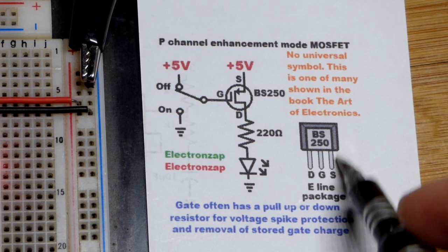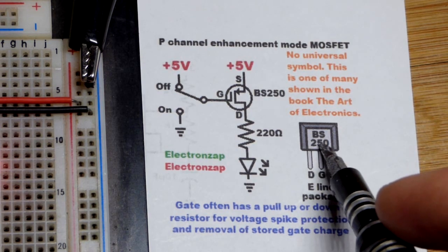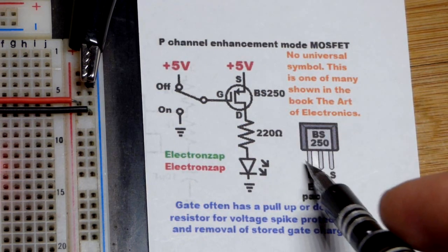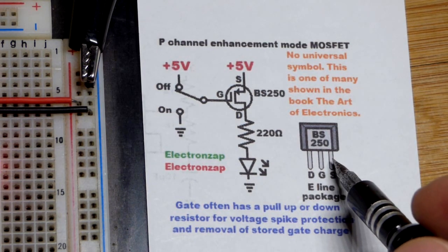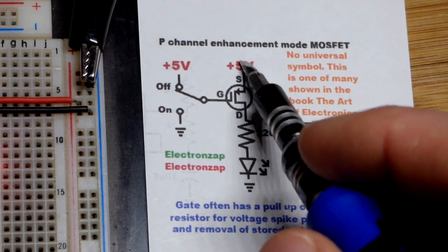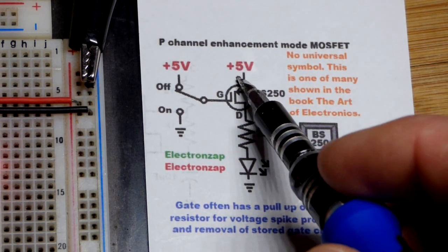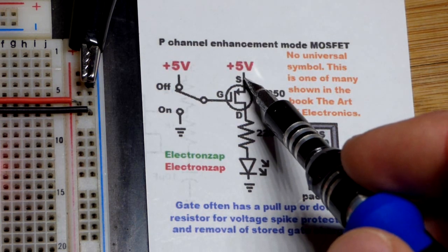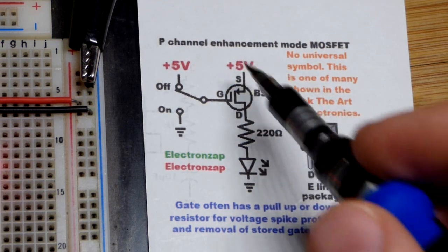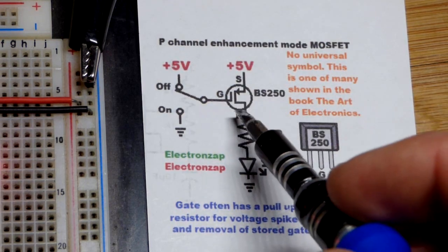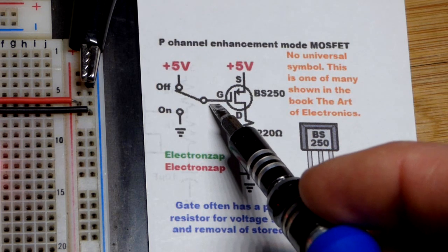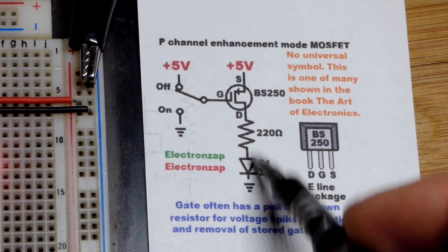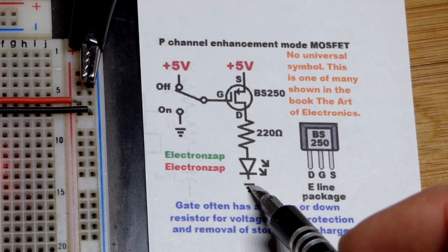But again, it has 3 pins. The front is the flat side right there. It actually gets larger on the back. We'll get to that. But left pin is drain, middle pin is gate, right pin is source. So the source goes to the positive supply. If you know bipolar junction transistors, that's where the emitter of a PNP transistor goes. It's much the same, but the inner workings are a bit different. Then we have the gate. It is the control, and then the drain is where we put the load when we're using this as a switch, going to the negative supply right there.